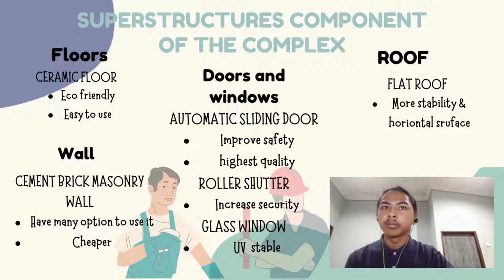The brick masonry wall has been chosen because the shape and size of masonry units are uniform, and brick masonry does not require highly trained labor. Bricks are also lighter than stone and concrete, easier to handle and transport and less expensive. Brick walls are thinner and depending on structural needs, units can be bonded with various types of mortar.